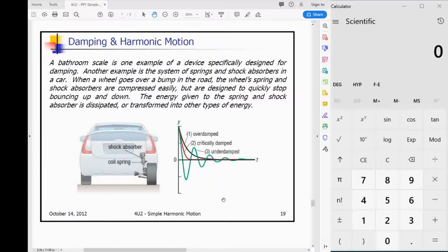So in terms of what each of these three types of responses look like, the faster we get to a flat line on the 0, the better the system is, depending on our applications, but that's what it is in most cases. Now, the underdamped system has a large overshoot, and the overshoots after that start to decrease.